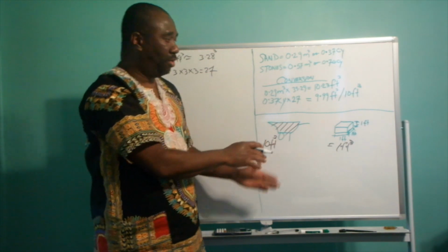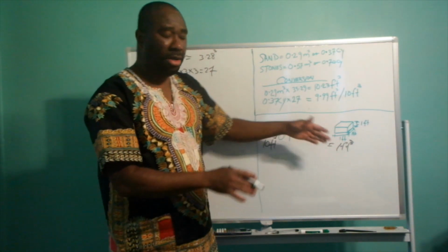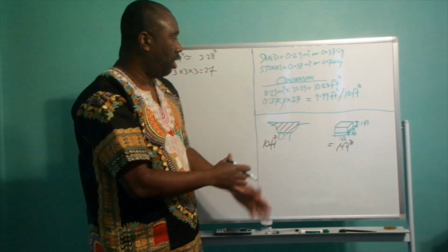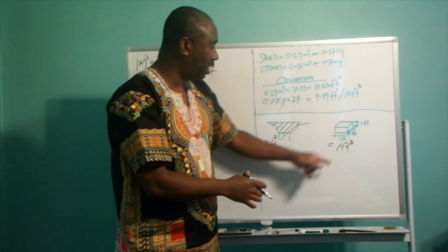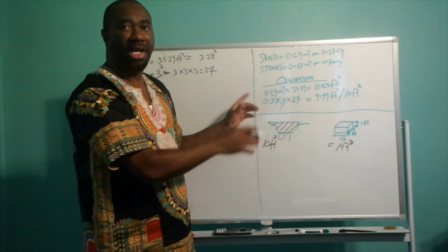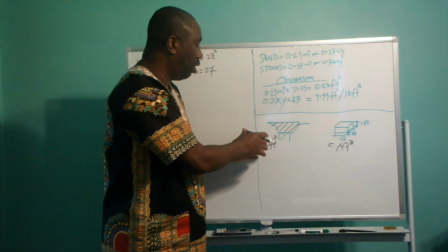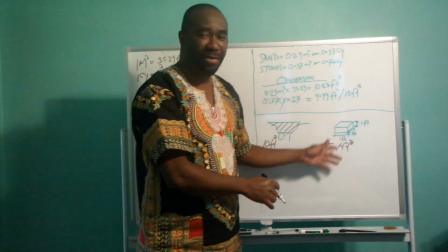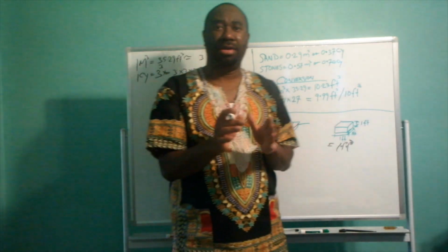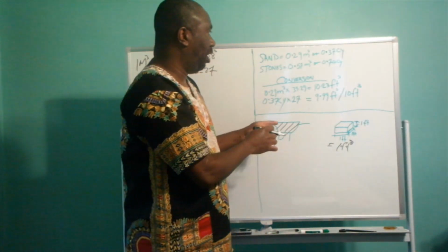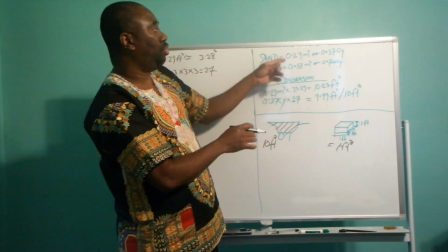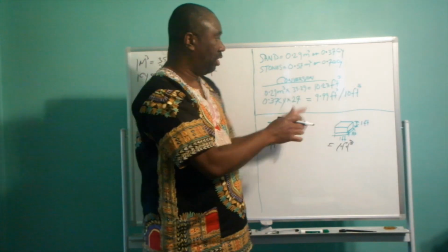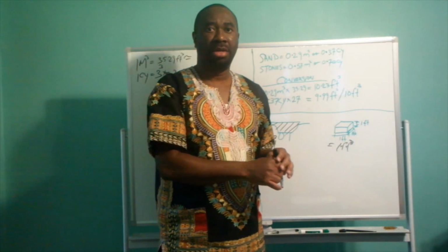I'm not saying that in this instance, based on my calculation. Just to show you a better way, you can just use your measuring box and fill the barrel, and then you will know how much your barrel measures. So that's a way you can simplify the measuring on your site using a wheelbarrow, instead of talking about using decimals on meter cube and cubic yard.